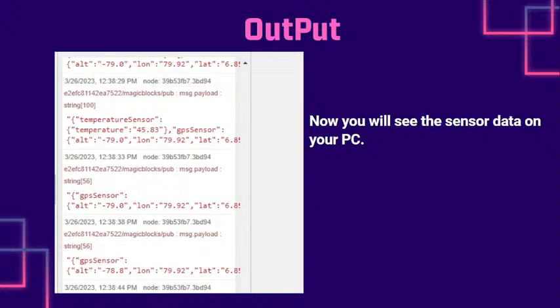So we have discussed today altogether 3 types of activities. First activity is the real-time weather station. We use the Magicbit and DHT11 sensor as well as the onboard LDR in Magicbit, and using the Wi-Fi as the connection or the gateway to connect between the Magicbit device and the Magicblocks IoT cloud platform. We have measured the sensor values, and then we have created a dashboard,